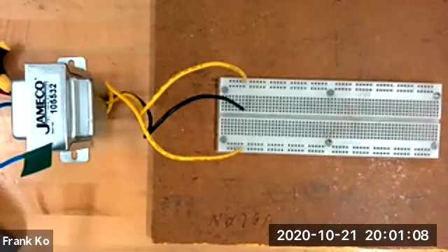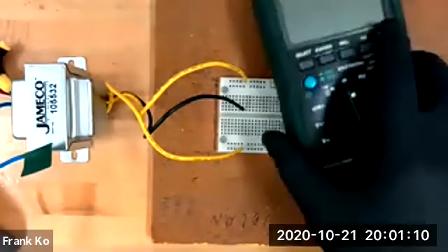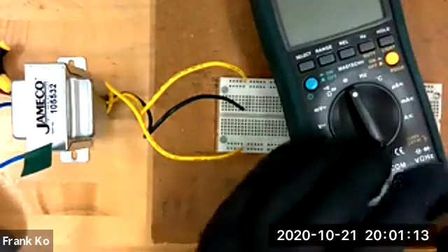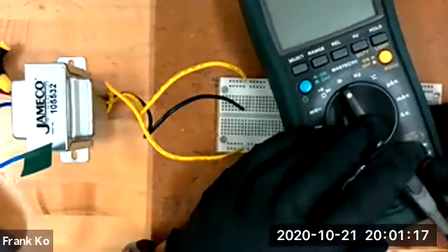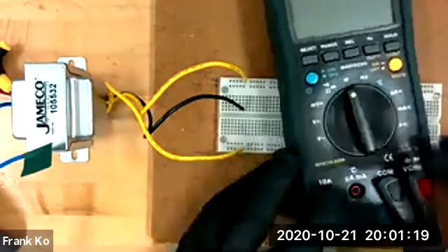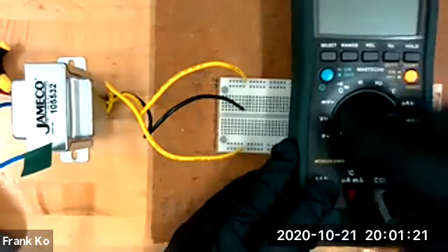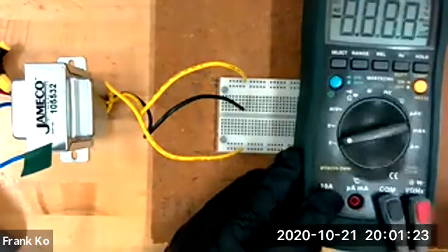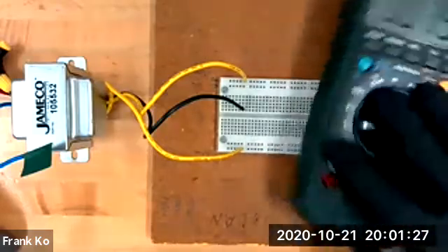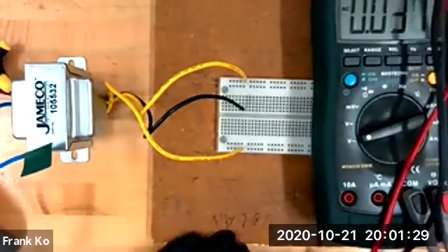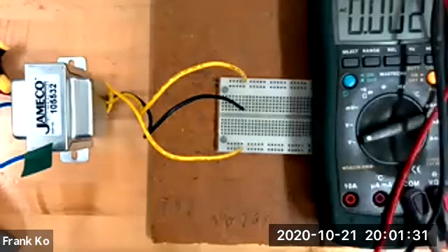All right, so now we're ready for our digital multimeter. So you get out this bad boy, plug in your common, your voltage, to the voltage position, like so. Set this up for AC voltage, there. Turn the machine on. And let's go ahead and see in a moment what we're gonna have on our secondary.